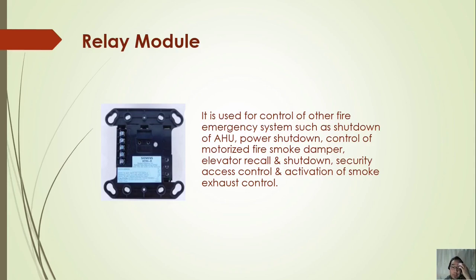And the other one is elevator recall. Elevator recall, guys, is just to bring the elevator down to the ground floor or the level for evacuation. So if a fire starts in the building and the fire alarm triggers, and people, let's say, are inside the elevator on the 26th floor, once the fire alarm is activated, this elevator will automatically go to the ground floor. From there, it will stop and open. It will not close anymore. It will stay open, so people cannot use the elevator, and they can just go out from the elevator and evacuate from ground level. So this is the one.